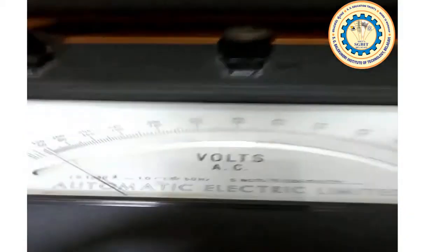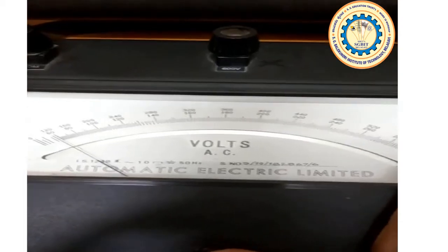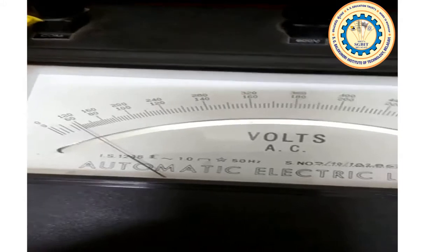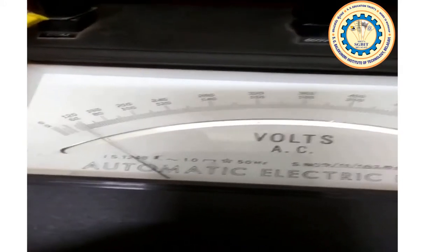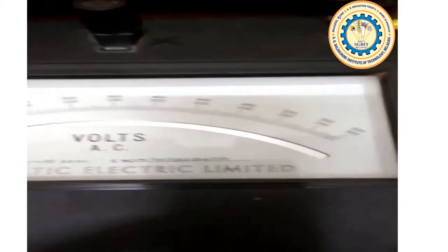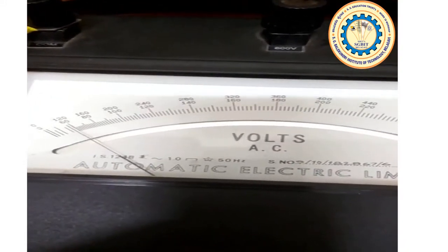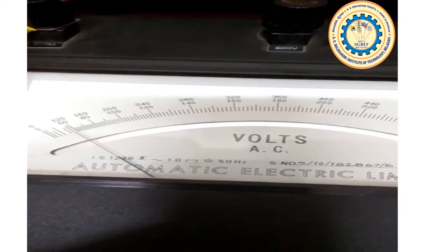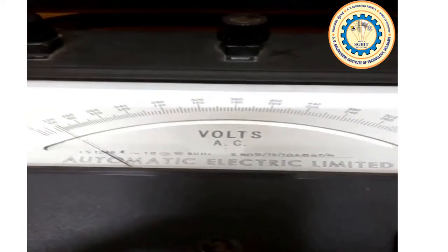Next, this is the voltmeter which is across the rheostat. So this will give the reading VR, that is the voltage across the resistance. Here we have connected the 300 range, so you have to read the below scale for the 300 range. Now it is almost equal to 60. So this is 30, 50, 58 it is. So note down VR as 58.